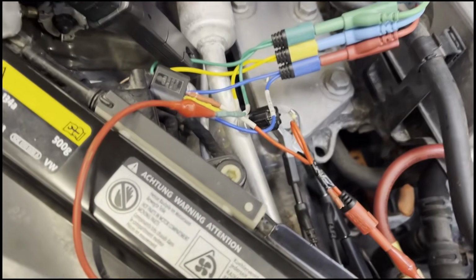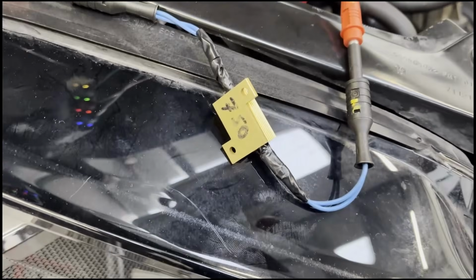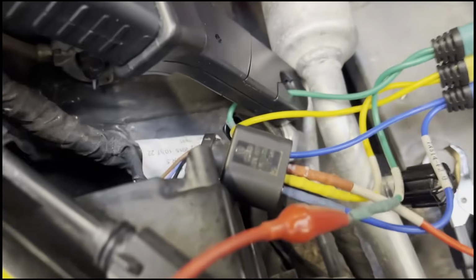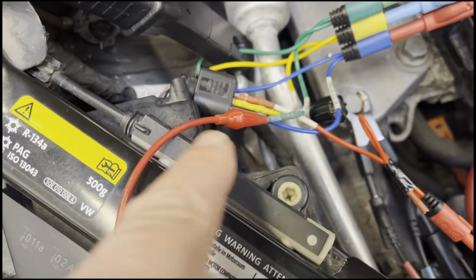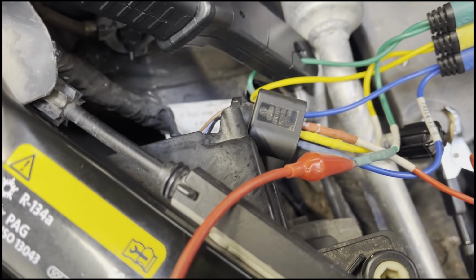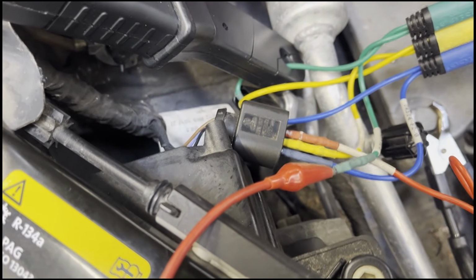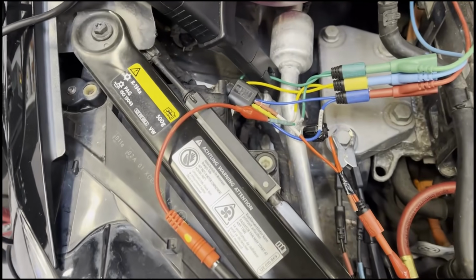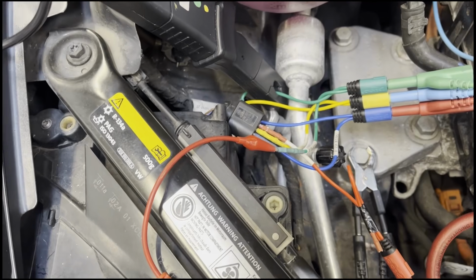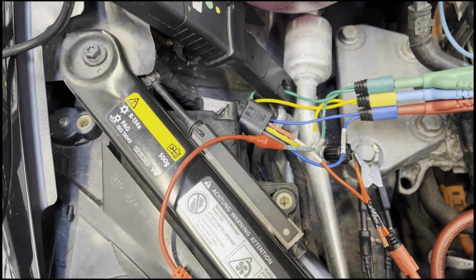So here we have added the resistor. It's a wire wound resistor, a 750 ohm. You'll see that the green wire that comes from the pressure switch into our breakout cable, whereas it went originally into the connector here, will now go through this 4mm breakout, through the resistor, and back into the harness connector. So basically we now have 750 ohms resistance in the ground line between the air conditioning switch and vehicle ground.